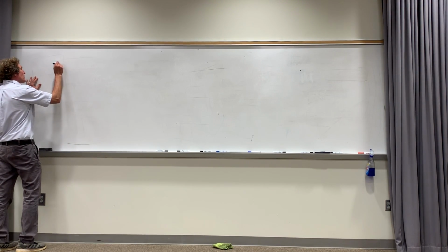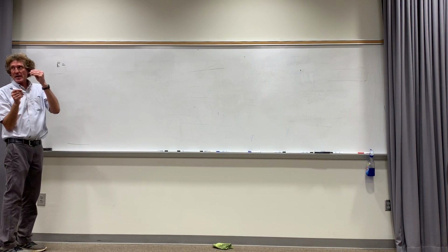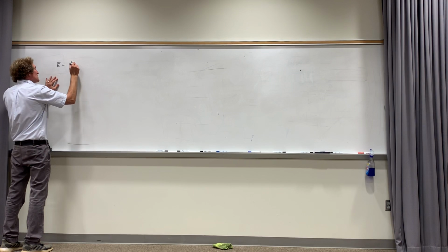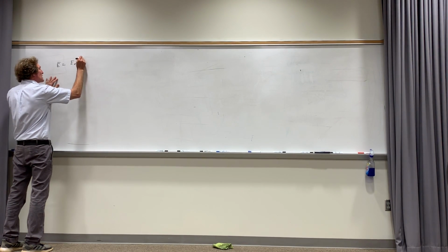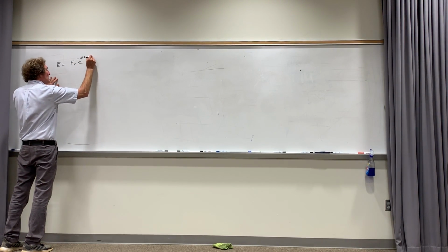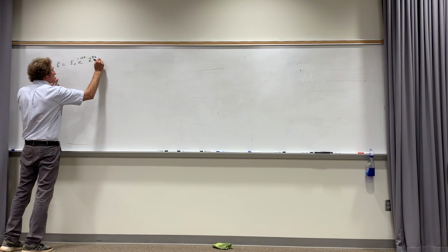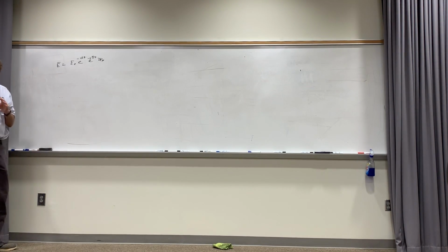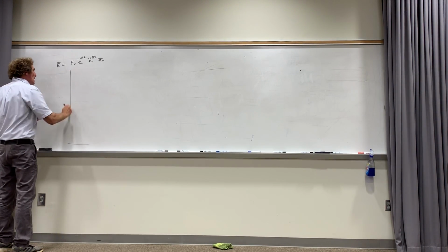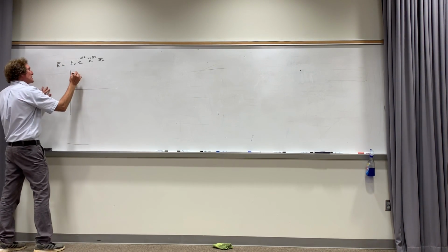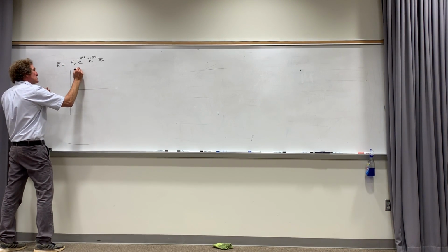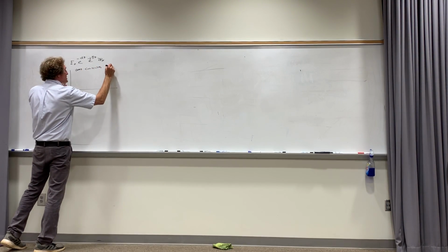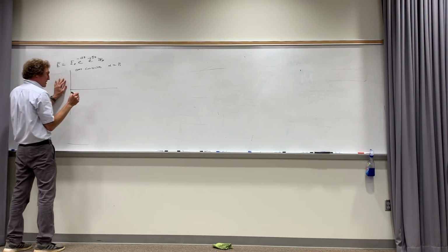You know the general formula for an electromagnetic field, if it's propagating in the z direction, but it's oriented in the x direction, and this is just a positive traveling wave, it would be some E0 e to the minus alpha z times e to the minus j beta z, right? And it's in the x direction. Now, try to appreciate what I'm doing. I'm going to say I have something, and this is going to be a very good conductor, which means alpha equals beta.